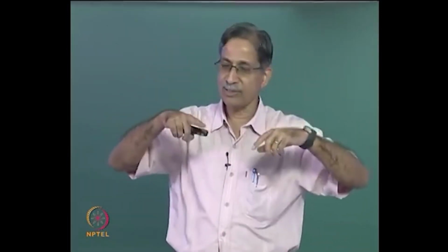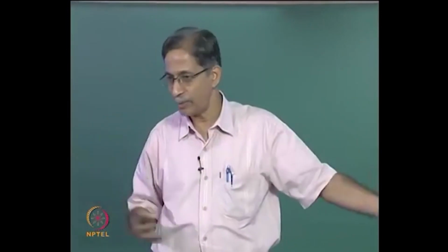Because we really want to find out what's happening to our 4EI by L, 2EI by L, 3EI by L. That's our real interest. We are now in a position to do that, because in the previous case we looked at a beam with an axial force P and some loading acting on it, and we said if it's concentrated it's something, if it's UDL it's something, we can work it out.